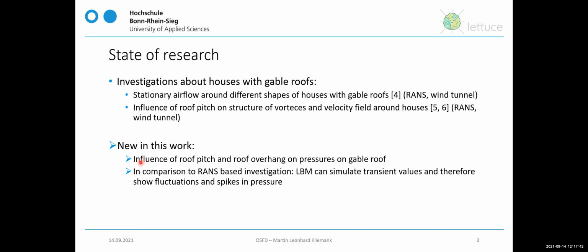So now, new in this work is the focus on the pressures on the roof, which result in, for example, the suction that sucks away the shingles from the roof and are therefore the actual cause of the damage. I want to specifically focus on the influence of the roof pitch and the roof overhangs on these pressures. And since I'm using the Lattice-Boltzmann method, in comparison to the previous investigations there's also the advantage that there are better possibilities to look at transient values, and therefore also investigate the fluctuations and spikes in the pressure.